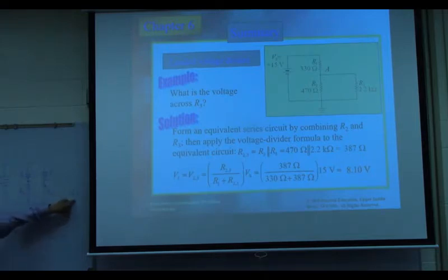Does this change? No. Why? Because it equals zero. Because this voltage here is in parallel, so this here is always equal to Vs. This one is a voltage divider, right? We don't care about this part. So this is total Vs. Vs is only multiplied by this divided by the sum of these two. So we don't care about this, we don't care about this.